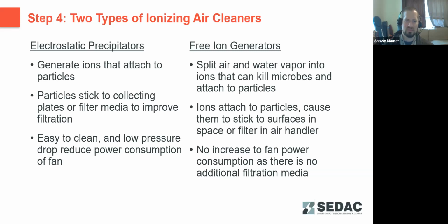It's a favored system because it has a very low pressure drop, so you don't have the impact on your fan energy consumption like you would with increasing filtration with filter media.